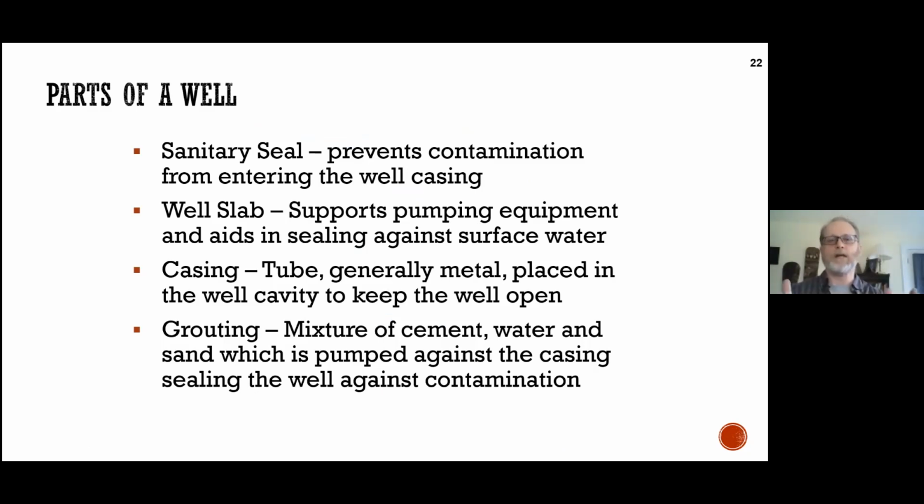The casing, in the case of a drilled well, is typically steel. And that holds the surrounding ground, otherwise it would collapse and then your pump wouldn't work. Remember, in a hand dug well, that can happen, right? There's no supporting material installed. It's just dug into the topsoil and overburden and through the supporting soil. Well, over time that can erode and fill up that well space.